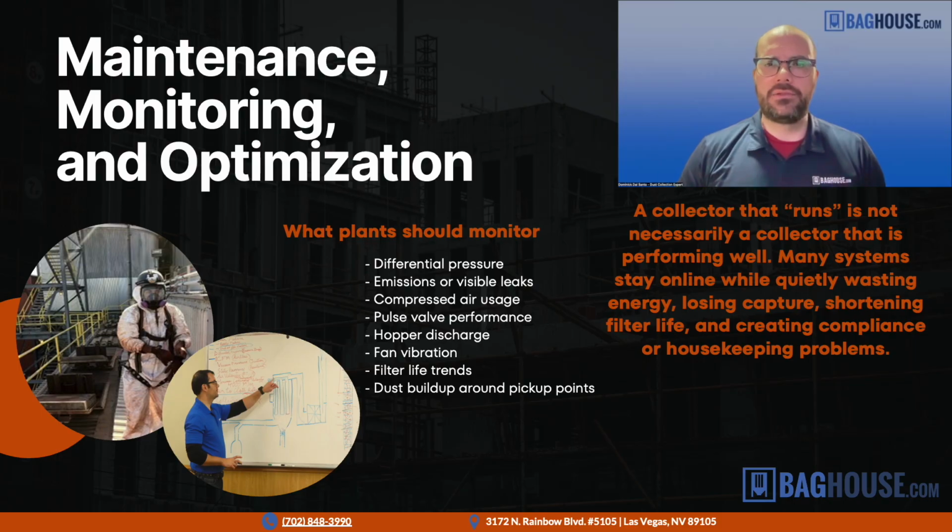Okay, lastly, just a few things we want to mention with maintenance, monitoring, and optimization. So every single dust collector in your plant should be equipped with a differential pressure gauge, and it has to be working. It's one of the most tedious and most routine things that we can do, but it's the first thing we mention whenever we do a visit: making sure the differential pressure readings are accurate and reliable.